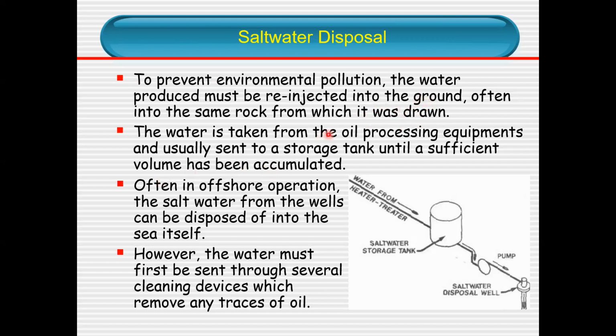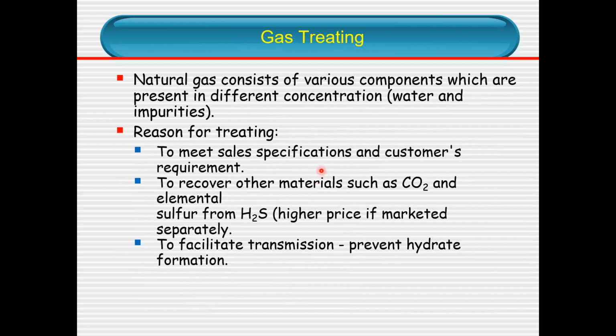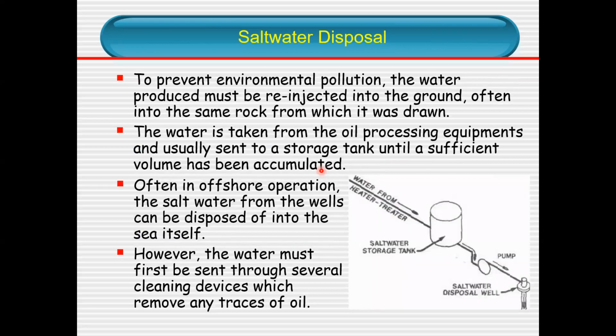The water is taken from oil processing equipment and usually sent to a storage tank until sufficient volume has been accumulated. Often in offshore operation, the salt water from wells can be disposed of into the sea itself after it has been treated. You cannot just throw off this untreated water. However, the water must first be sent through several cleaning devices which remove any traces of oil.